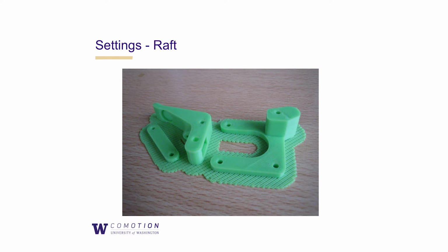Then another really big consideration is rafts. Rafts are needed for the 3D model to adhere to the printer bed. Some designs will adhere better with a raft, and will come out much better with a raft. Generally, a raft is used to make a connection between the 3D printed piece and the level bed.